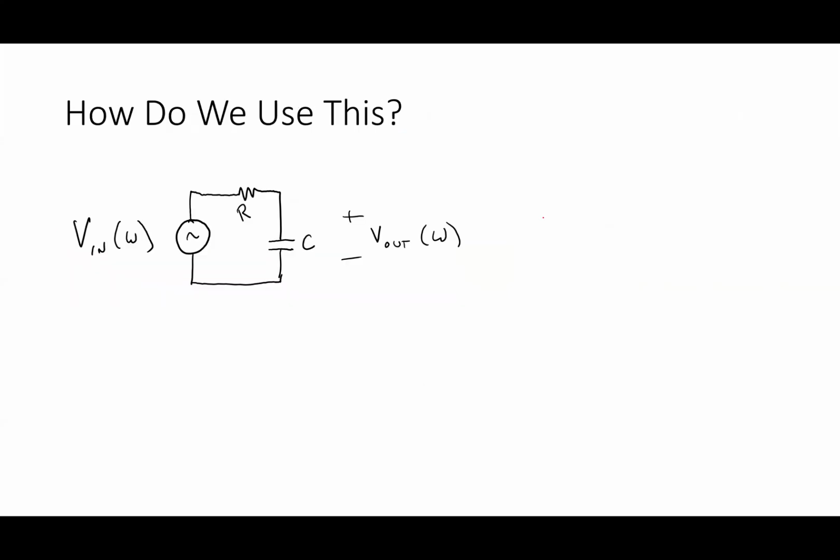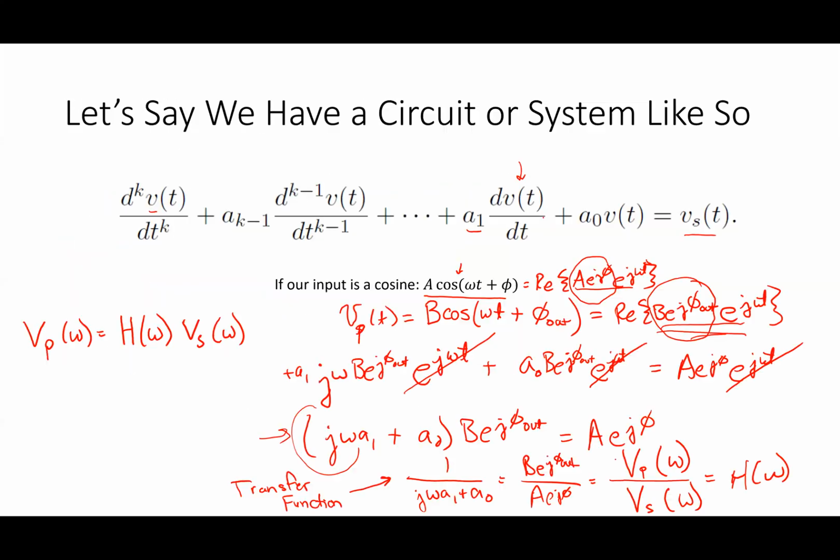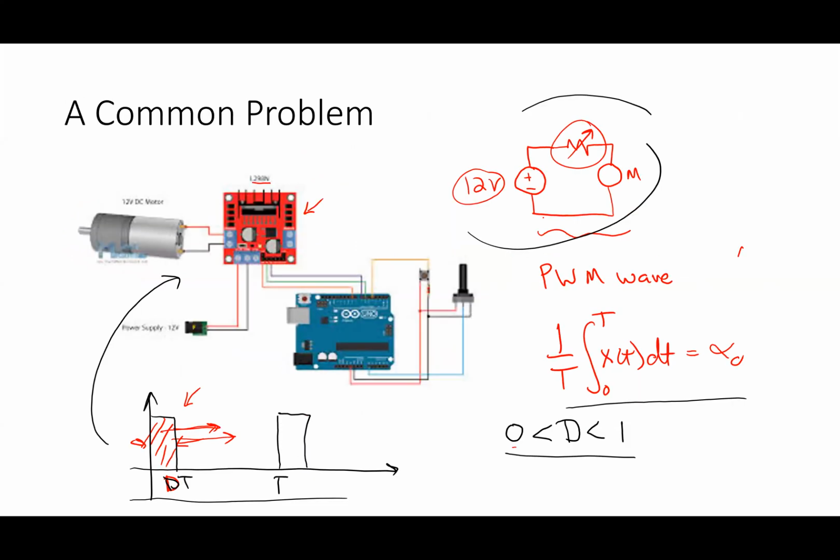So what I did when I showed that thing with the motor is essentially the motor has some transfer function h of omega, which is basically the output is the speed and the input is the voltage that I apply. If I know the Fourier transform of this voltage, which exists in the time domain, V of t, and I know the transfer function of the motor, then I can figure out what the speed's going to do.